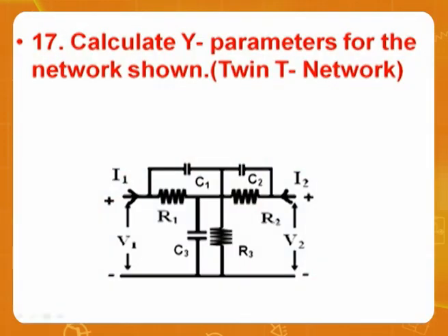If a low pass filter and a high pass filter are connected in parallel, what do we do? Like we studied in the previous topics on filters, I already talked to you. There in the filters we talked about LC, but here I am talking about RC, it doesn't matter. So low pass in parallel with high pass, or high pass in parallel with low pass, will automatically mean the Y parameters get added. So you can calculate the Y parameters of each circuit and finally add them. The respective components are added, and that is the best, easiest procedure.